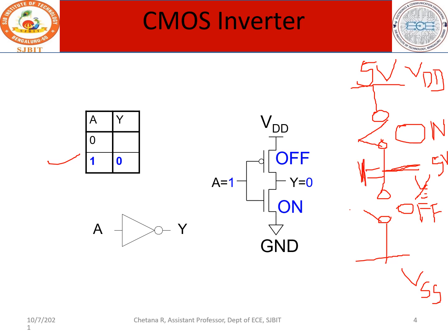Therefore, initially when your input is 0, the output is 1, and that is how the truth table condition is. So, this combination, by constructing a PMOS in the pull-up region and an NMOS in the pull-down region, behaves as an inverter. Hence the proof. Therefore, this is your ideal CMOS inverter. With proof, you have to check only with the justification of the truth table. So, this is the conclusion of a CMOS inverter.